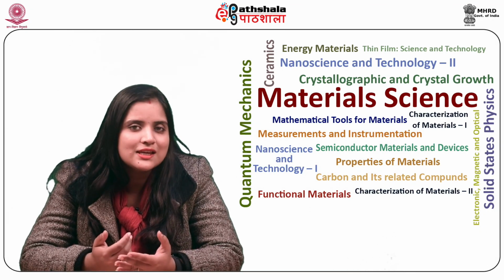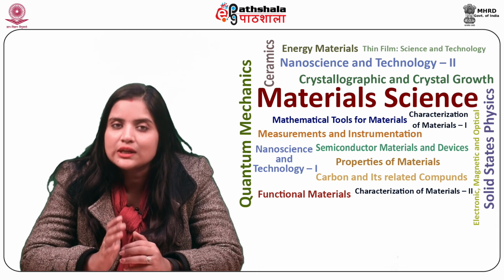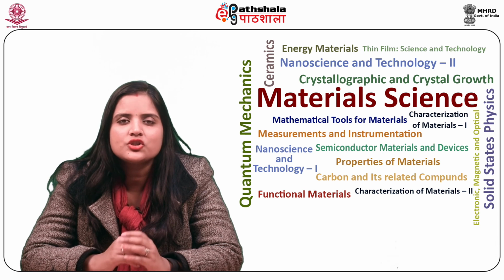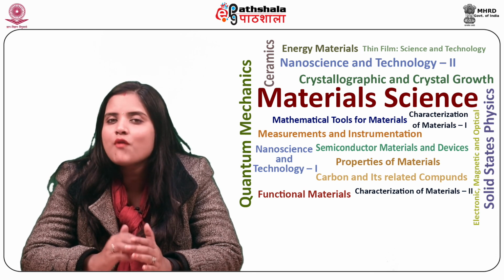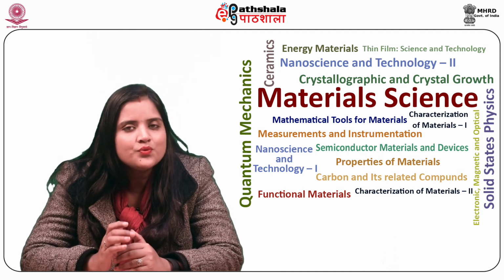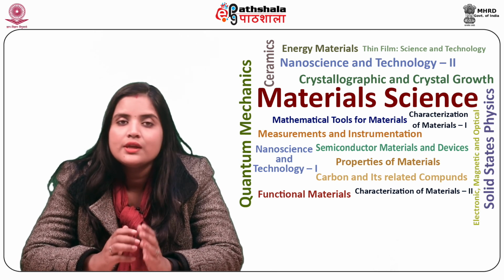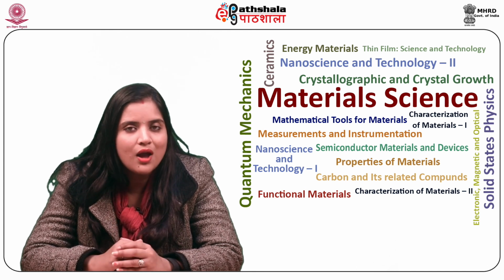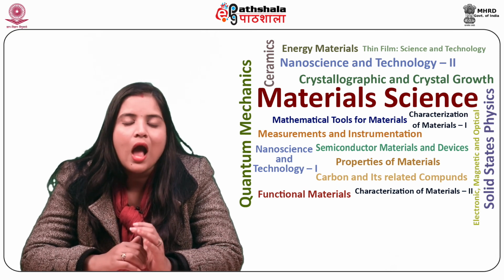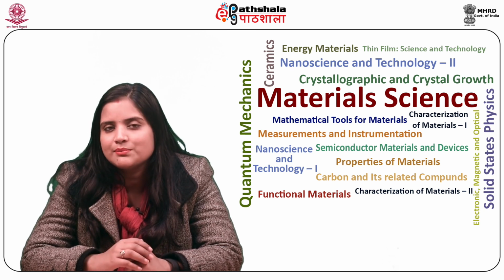Let us next discuss the disadvantages of the gas phase condensation technique. The products, which are to be separated from the gas stream, have relatively high volume. Good filters are often required to do the job. Secondly, the process requires highly pure precursors, which may be expensive as purification during the synthesis is not possible.